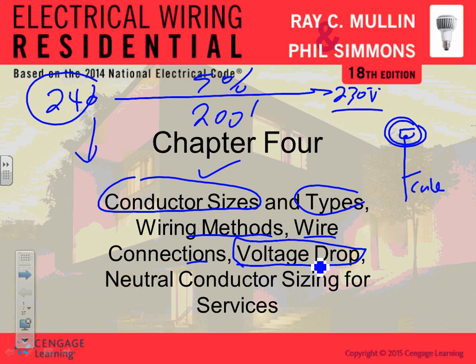The neutral, and I told you guys the beauty of the NEC code, the beauty of the three-phase system, and why the three-phase system is superior, is because you can take 3 wires, and if you balance the load, the 3rd wire is carrying nothing, the 4th wire is carrying nothing, right? So the neutral always carries the unbalance between the 3 phases. Anybody remember what the exception that we talked about, Jay? Harmonics. Harmonics are the exception.